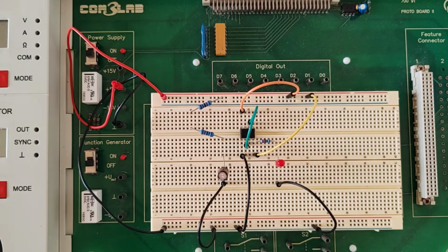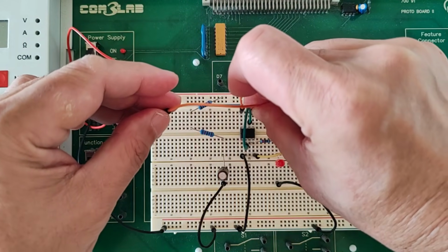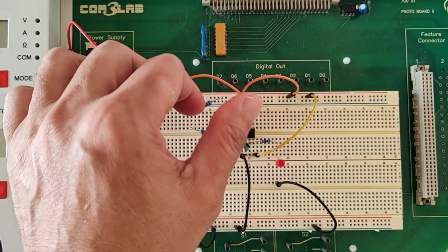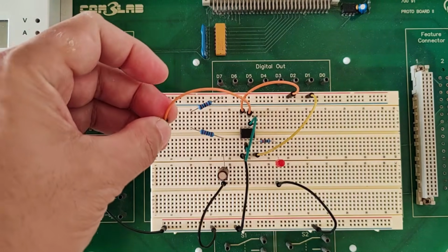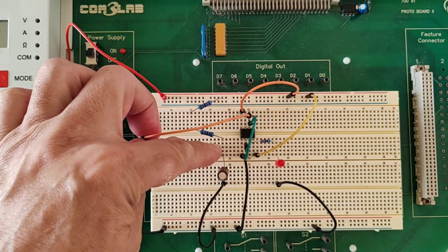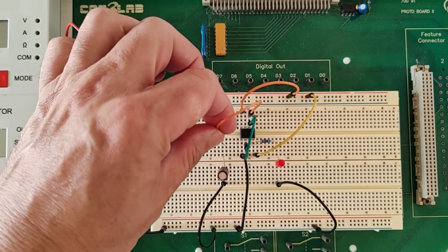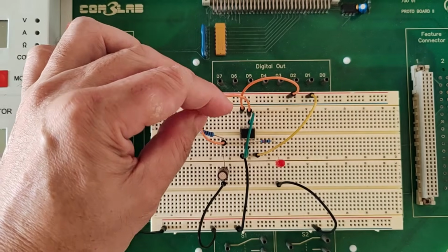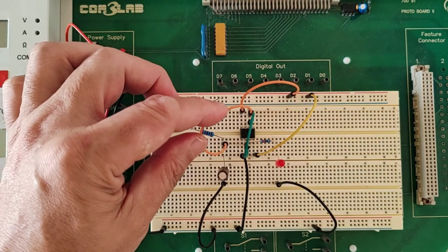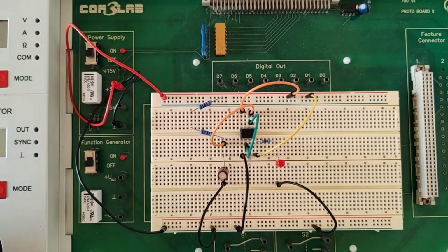And pin number 6, the other side. Let's have another jumper wire on pin number 6. Here. The second jumper wire coming from pin number 6 will have to be connected to the junction between the capacitor and the second resistor, the 10 kilo ohm resistor. Let's do that now. There. Pin number 6 to the junction between.